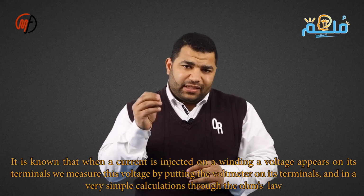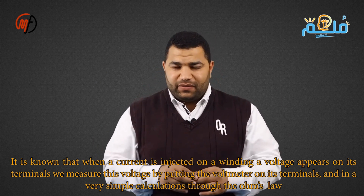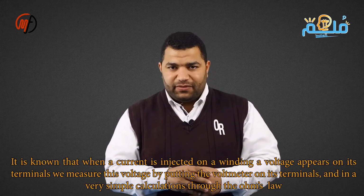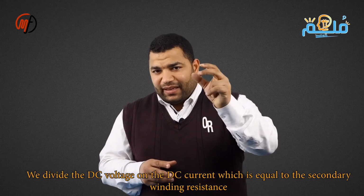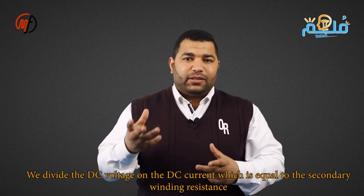It's known that when DC current is injected into the winding, a voltage is generated across the terminals of that winding. We measure this voltage by placing a voltmeter across its terminals. Then, using Ohm's law, we simply divide the DC voltage by the DC current to get the resistance of the secondary winding. This helps us evaluate any possible winding damage, such as short circuits between turns or open circuits, and ensures everything is functioning properly.